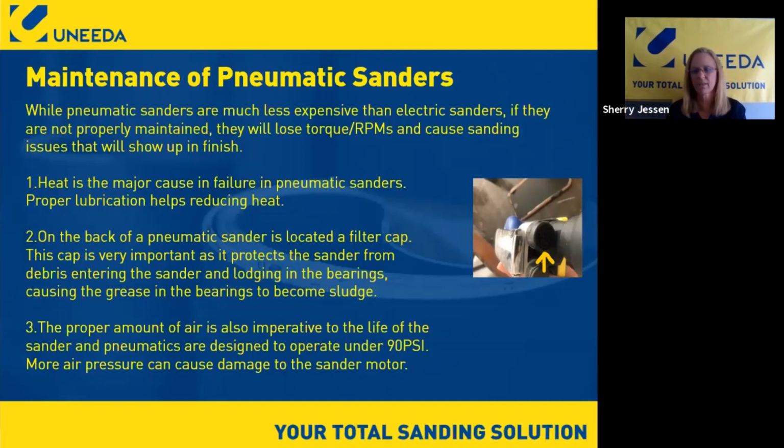People drop them, they knock the filter cap off. Well, it won't hurt. I'm just going to sand this one little piece. It won't hurt just to do this one little piece. It will hurt, because every time you do it, again, the dust is going in the filter and it's getting into the bearing. So getting that set up, a good maintenance schedule, either with the people using your sanders, or